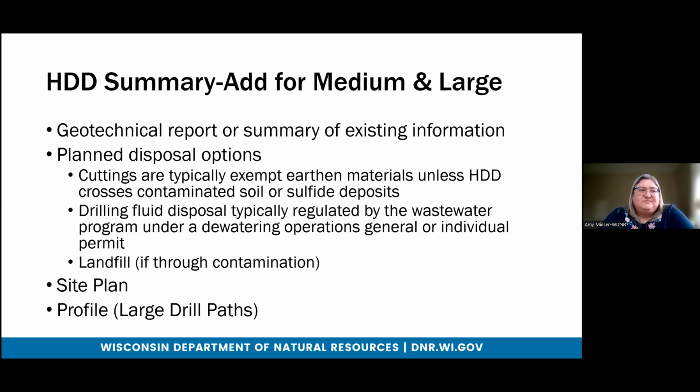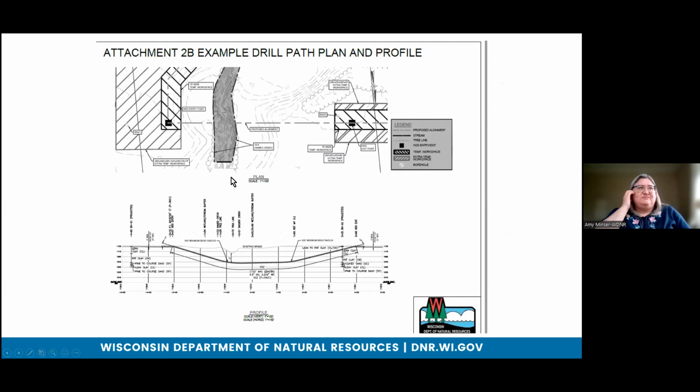But the drill fluid disposal is typically regulated by the wastewater program under a dewatering operations general or individual permit. But if the HDD goes through contaminated soils or sulfide deposits, that may need to be landfilled. We're looking for a site plan, and for large drill paths, we want to see a profile. And in the attachments, there's a figure showing the sorts of things we would hope to see on the plan and profile.